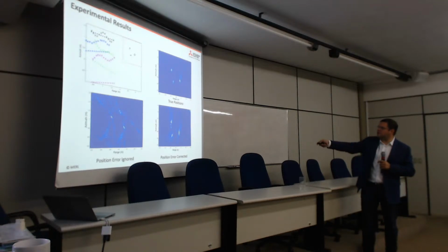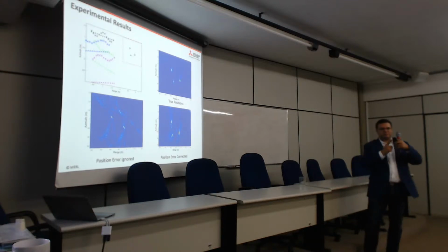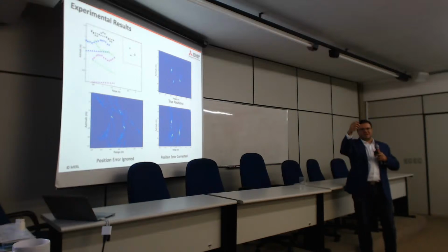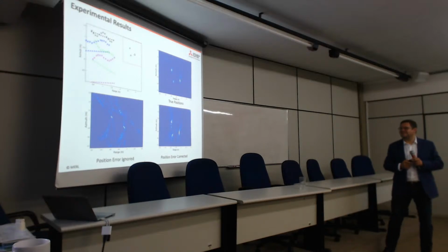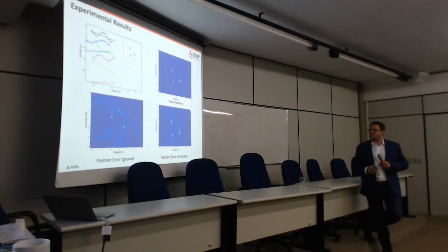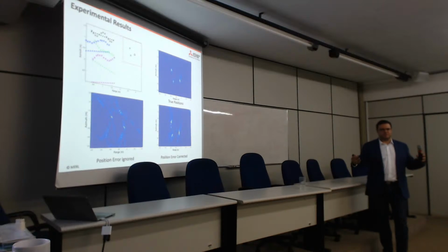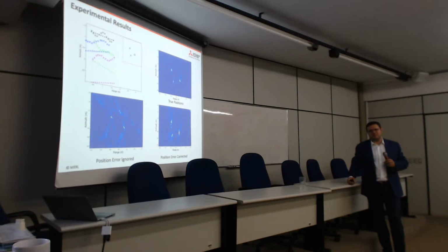No. And actually here, what is interesting is that because of the shift, what you see is a bit of the back corner of the room that happened to have 3 beams connecting, and it was one more corner reflector. So no, it wasn't an anechoic chamber. It's a true measurement, and that's why you get some multiple reflections. It wasn't a very dense room. It was an empty room with the array, but it wasn't an anechoic chamber.